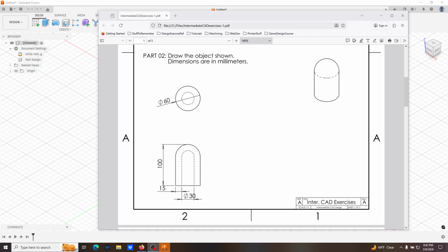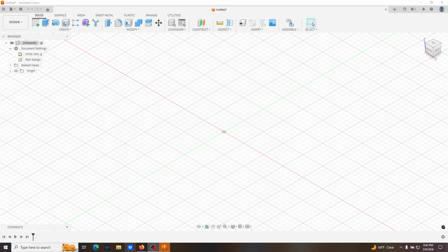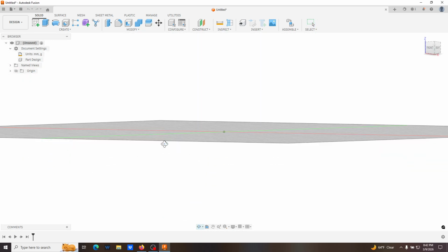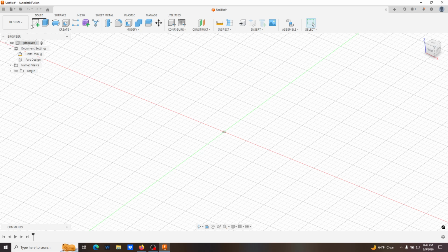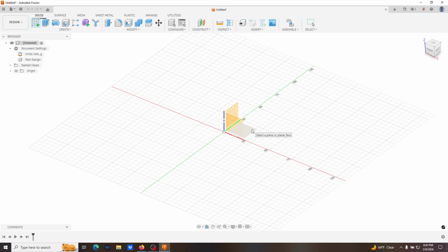So this one works kind of like an extension of the first example that we did. So the first way I'll start building it is just by going out from there. And again, one of the things that I want to highlight is that it really comes down to how you want to lay it out, being able to rotate your view or align it in a way. Just shift and the middle mouse button will let you rotate the view plane here. And so what I'm going to do is start by creating a sketch. And then again, orientation isn't too big of a deal, but I'm just going to go ahead and rotate it around. So I'll pick this top plane here. This should be the XY plane.